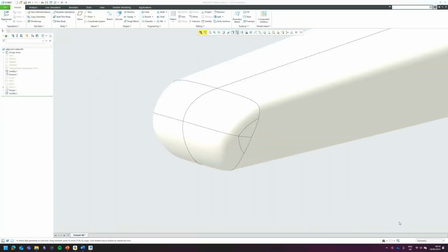These selection types are now more available within Creo. They were fairly restricted just to surface selection items in previous versions. They are now more available throughout a wider range of Creo Parametric. They're also persistent, so if you choose a trace selection, it's going to remain active as your selection method. But we can use these to grab a set of surfaces.